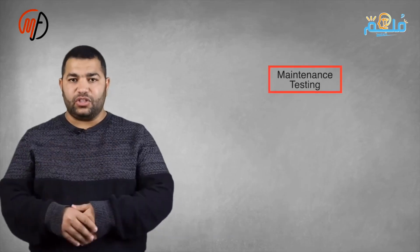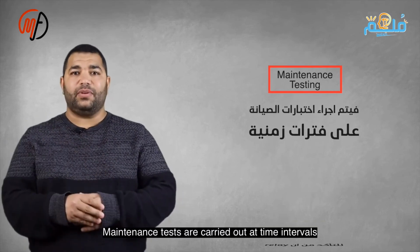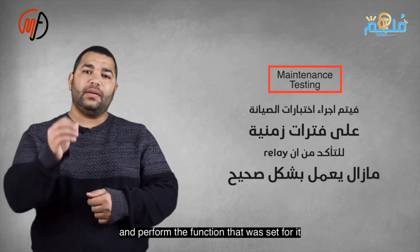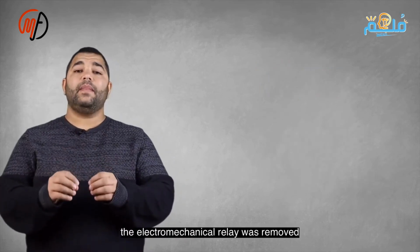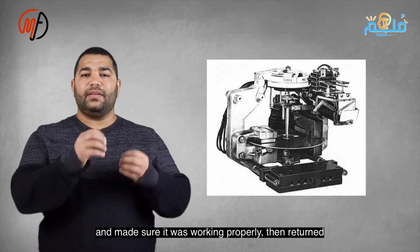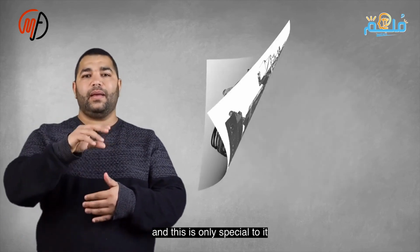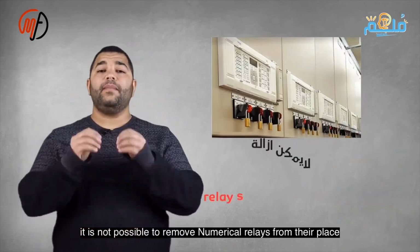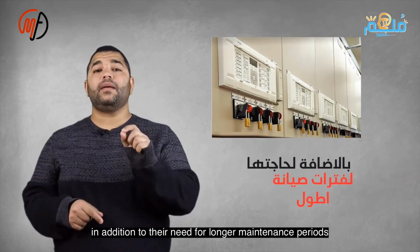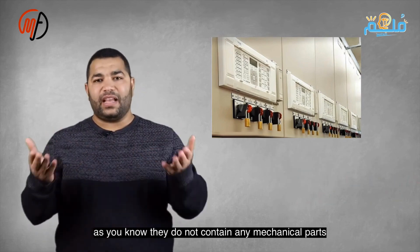Maintenance testing occurs after the station is in operation. Maintenance tests confirm the relay is still functioning correctly. Previously, electromechanical relays were removed, cleaned, and tested externally to confirm functionality. Now, numerical relays remain in place and need longer maintenance intervals due to the lack of mechanical parts.